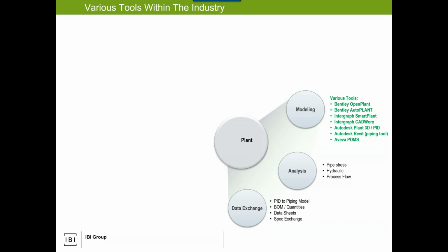The other thing, pipe stress and hydraulic flows. So hydraulic, if you've never heard of that term, my work with water treatment plants, basically water has to go from the lake through the treatment to a water tower to your tap, okay? Dependent on hydraulics. So I'm either going to pump the water everywhere it's got to go using a lot of energy, or I'm going to strategically pump and let gravity-based hydraulics do the rest of the work.